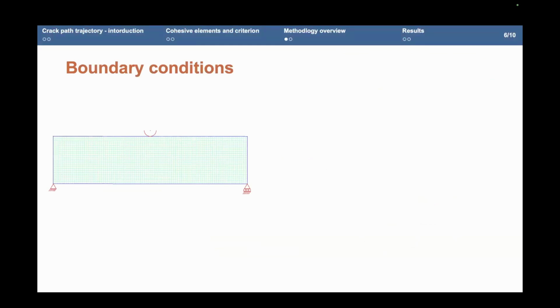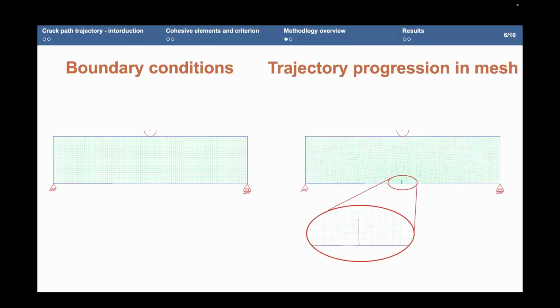So how it goes, we have a first simulation with some mesh. Now just engineeringly speaking, by intuition, the stress will be dense over there. We will have our principal stresses, and through the principal stresses, we get the versor as well. And perpendicular to this versor, it's most logical that the crack will go. It's not so visible over here, but there is a blue line which shows us where the cohesive elements will be. And also 4 points on the sides, unfortunately not so visible, that help us to always have a quadrilateral element for the precision.